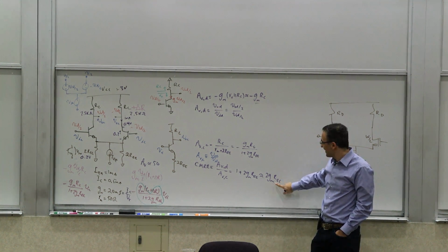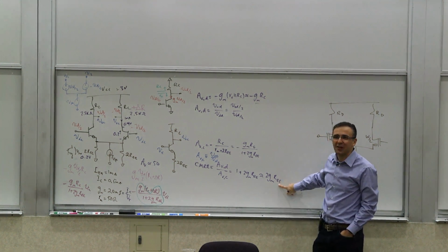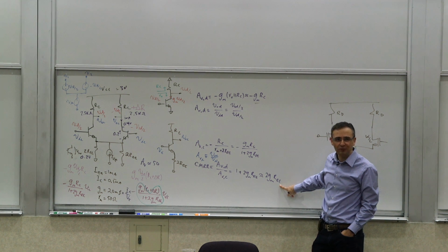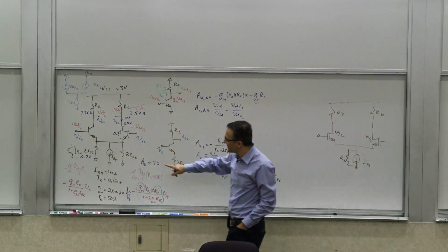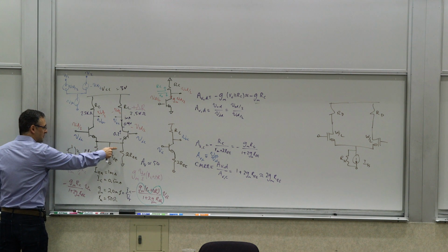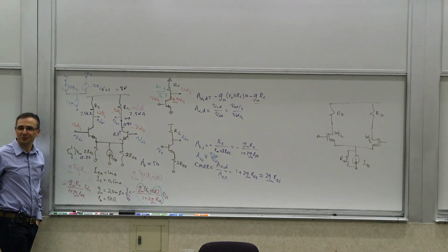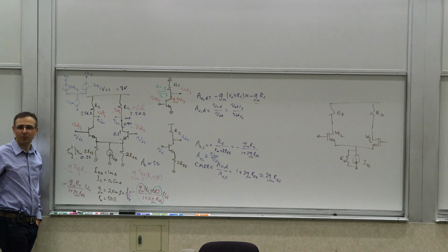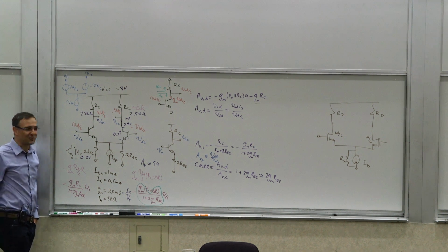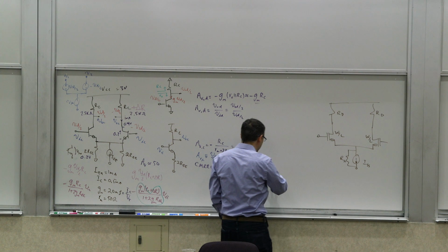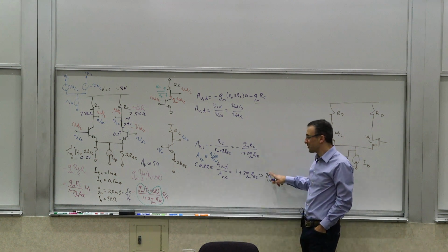That's right. But this REE, where is it coming from? This is the output resistance of the transistor you use to make this. This represents that output resistance, right? What is the output resistance proportional to? For bipolar, it's VA over IC. So this product remains constant because this goes up and this goes down.